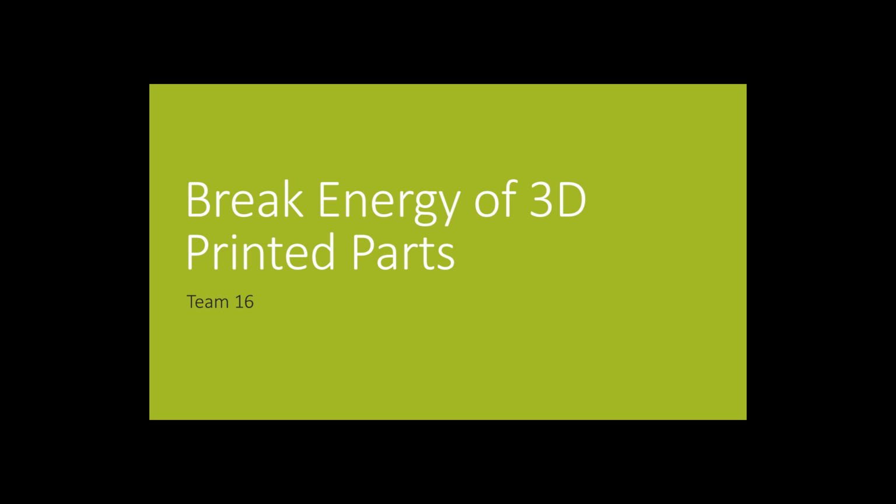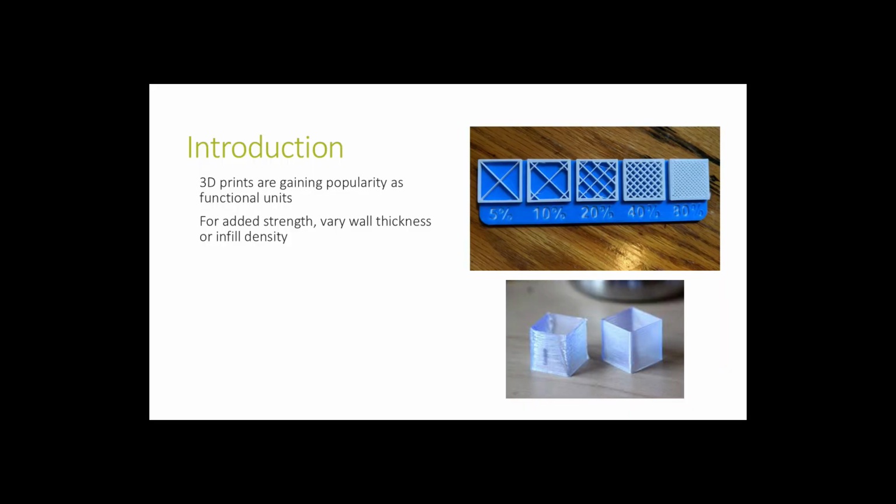The objective of this experiment was to determine a relationship between the break energy and the wall thickness of parts where the wall thickness has a significant contribution to the cross-sectional area. The product was tested in an IZOD impact tester, and a trend line was found with an R-squared value of 0.7879.